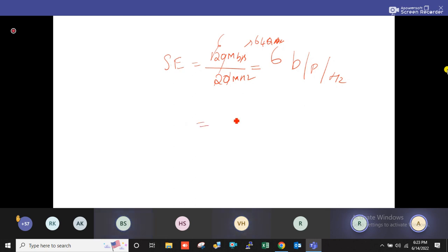If we go with, let's say, 16 QAM modulation, the throughput will be 80 Mbps, and with 20 megahertz constant, my spectral efficiency reduces to 4. So this is how we typically calculate the spectral efficiency in any technology. Maybe if you calculate in 3G, this will become 5 megahertz. That's the only difference. Okay.